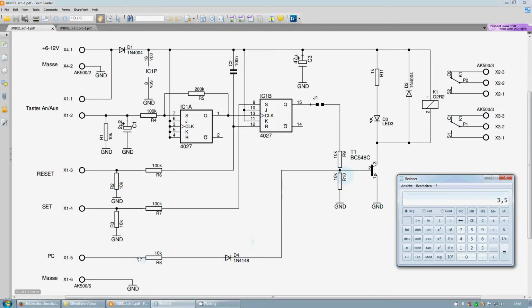And so 4.5 volts, or let's round it up to 5 volts, are 100% sufficient to switch the switching transistor on. And usually we use 6 or 12 volts for controlling the PC input. So when 5 volts are sufficient, then 6 or 12 volts of course will be sufficient as well. Now let's make a back of the envelope calculation.